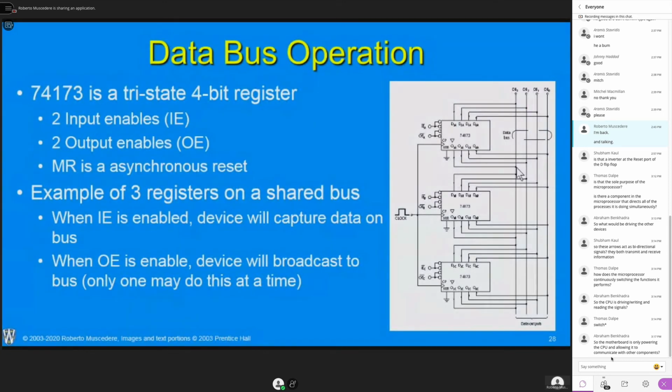And it's not a good thing because, for example, let's say D, our data bus, this bit here is being driven with a 1 from this component, but if it's being driven with a 0 from this component, now I'm connecting a 1 and 0 on my circuit, and that's going to cause a power drain situation. Okay, and that's not good. So we want to avoid those situations.